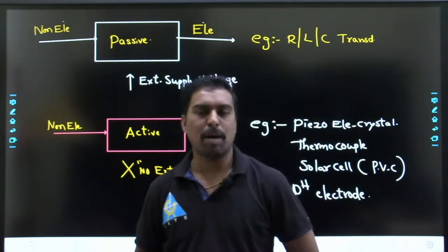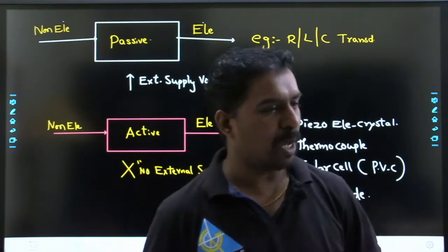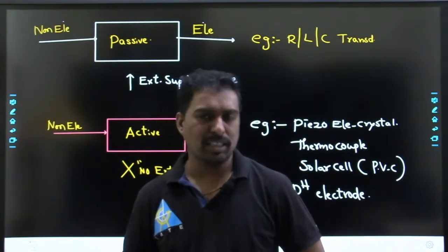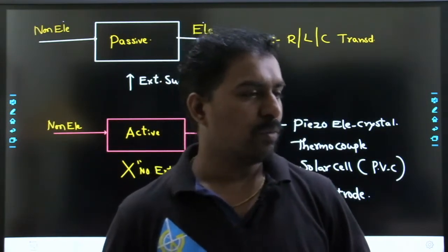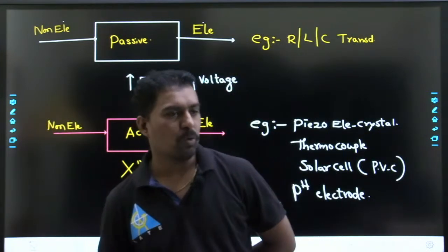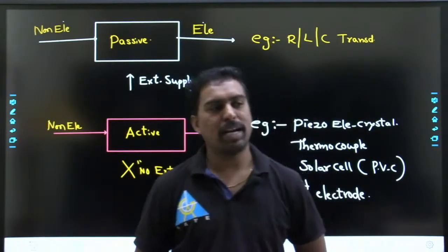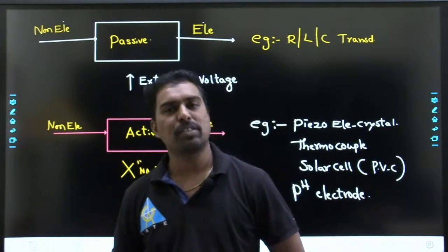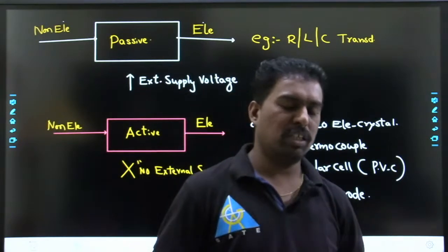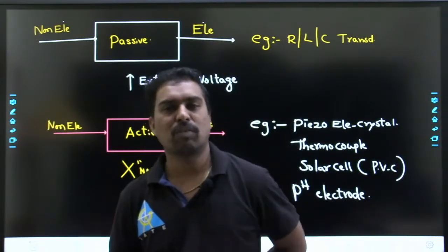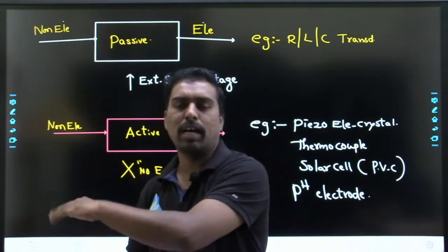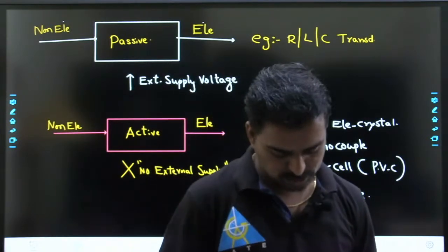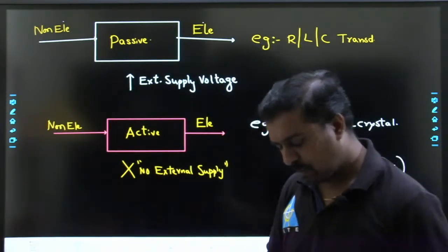If one spring is snapped, what happens? If two springs are damaged, what happens? If one spring snaps, and that spring is in series with the other spring, then definitely the controlling torque is not going to be there. Only the deflection torque will be there. Am I right or not? So the deflection torque will be more than the controlling torque. That's why the pointer will go to the maximum point and then come back. If the two springs are damaged, then there is no current passing. All these things we have discussed.